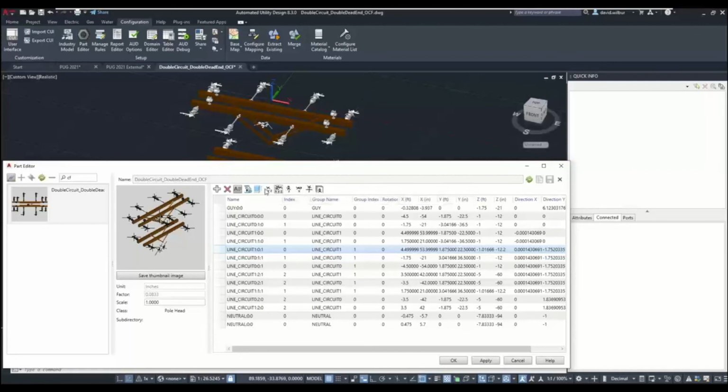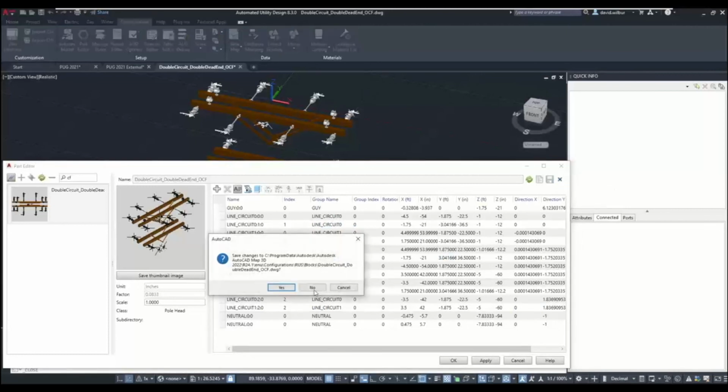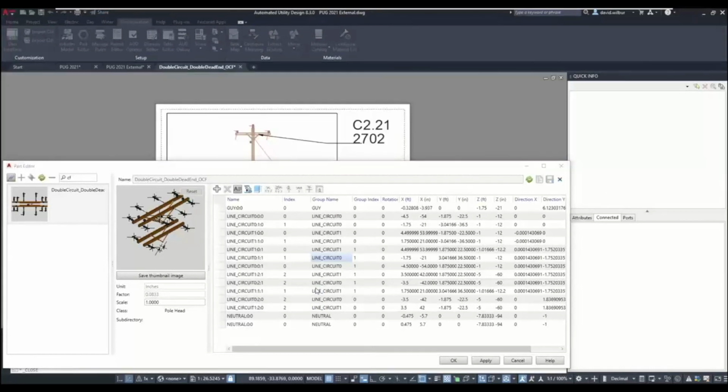This provides placement tools, so this makes it much easier to position and orient the ports and define them. There are automatic naming options that will allow the ports to be named automatically. Their types can be specified through a drop-down. So again, if you're already familiar with the process for authoring this, this dramatically improves the ease with which you can author that kind of content.